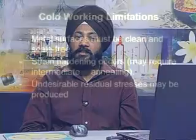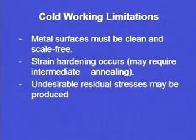Now, there are other cold working limitations, like metal surfaces must be clean and scale free. Already we have discussed that the surface of the metal that we are getting after the cold working operations is free from any kind of contamination, but before working we have to make sure that it is clean and there is no scale present on the surface of the metal.